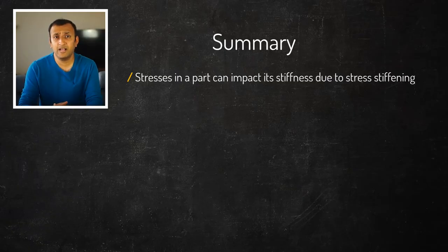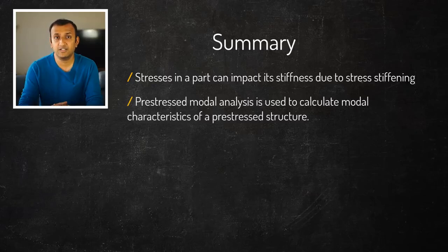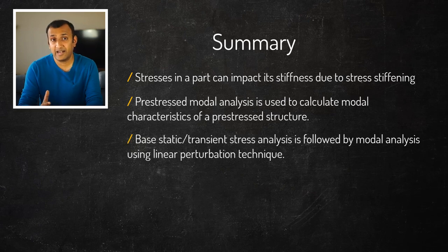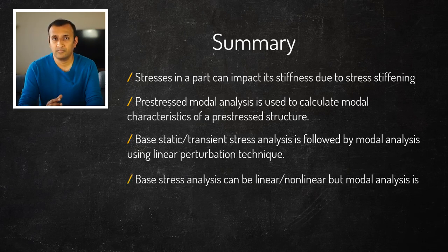Stresses developed in a part change its overall stiffness due to stress stiffening, and this can change its mode frequencies. A pre-stress modal analysis is used to calculate the modal characteristics of a structure with inherent stress. A base static or transient analysis is performed to calculate stresses, followed by a modal analysis using the linear perturbation technique. The base analysis can either be linear or nonlinear, but the modal analysis is linear in nature.